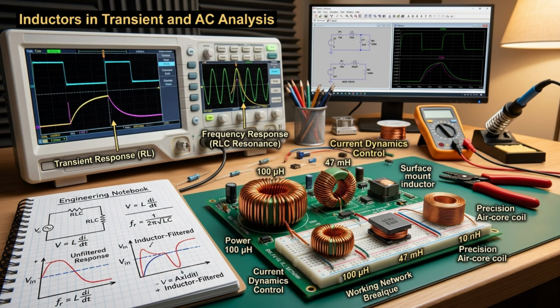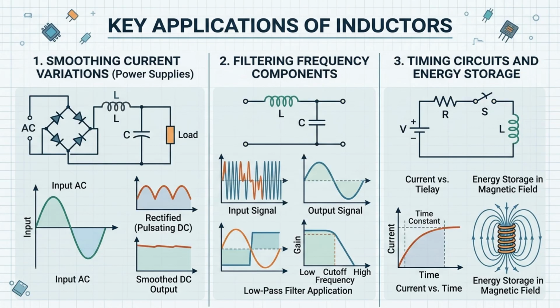In practical circuit design, inductors are essential in transient and AC analysis, especially in RL and RLC networks where time-dependent behavior defines system response. Engineers use inductors to control current dynamics, shape signal waveforms, and manage energy flow in both analog and power electronics systems. Inductors are widely used in power supplies to smooth current variations, in filters to separate frequency components, and in timing circuits where controlled delays are required.